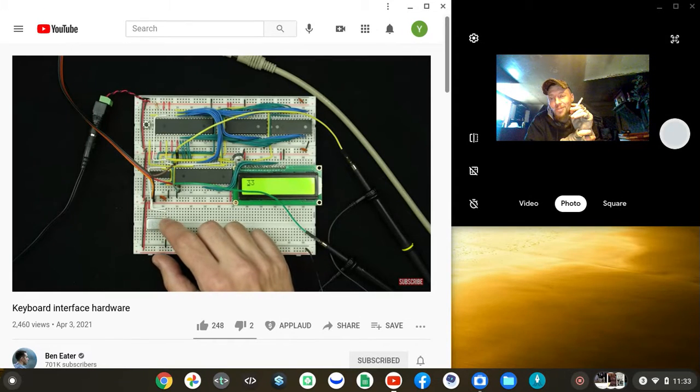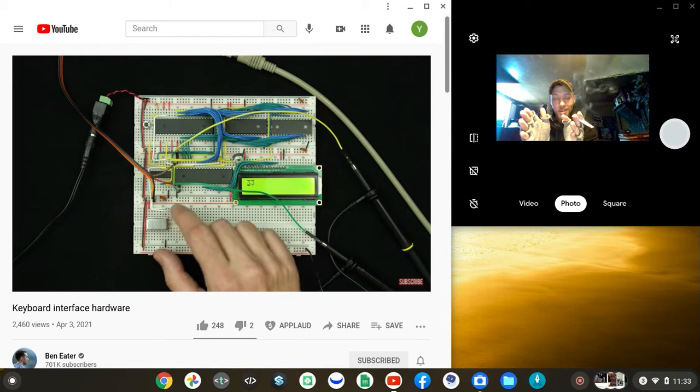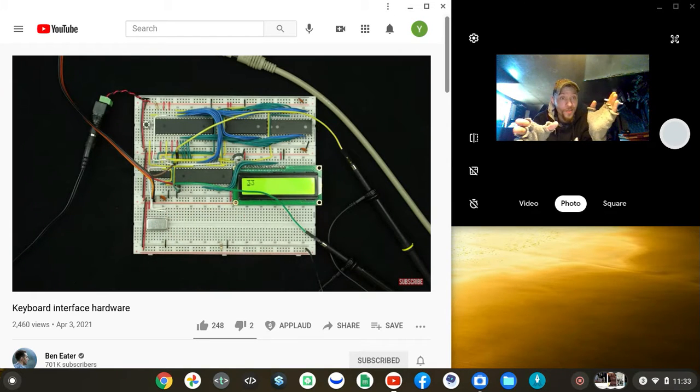every microsecond. So 85 microseconds is 85 clock cycles. So we're gonna get an interrupt every 85 clock cycles, and that doesn't really give us the opportunity to run very many instructions per interrupt. Another way to look at that is, if we use a separate interrupt to read every individual bit,